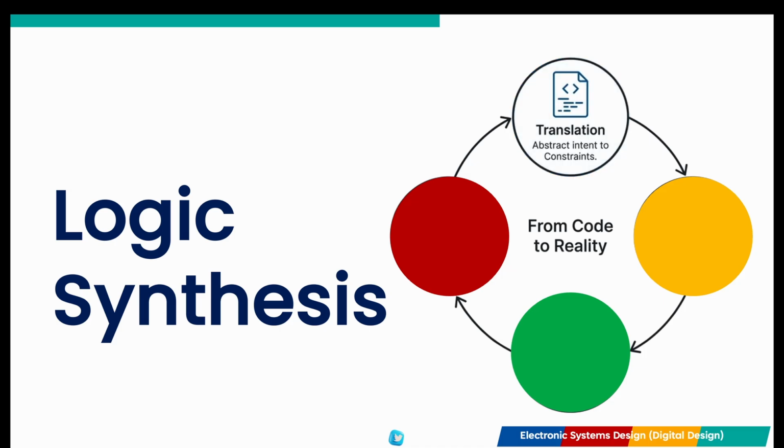This is where the tool takes your abstract intent, your Verilog code, and combines it with your timing constraints, the SDC file. The tool needs to know not just what the logic does, but how fast it needs to be.